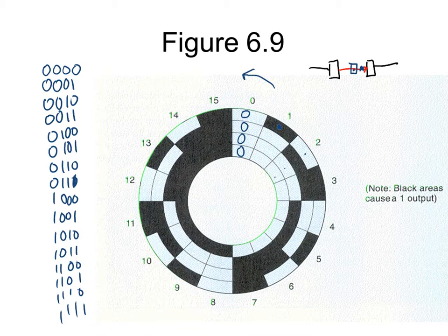You see that? Now this is binary, and a lot of people call this the 1248 code because this is the decimal weight that binary holds. It goes 1, 2, 4, 8, 16, 32, 64. And then what we do is we just look at the weight that this column holds. So let's look at this one right here. This holds a weight. If it's a 1, we add it. If it's not a 1, we leave it off. So we follow this column right down here.